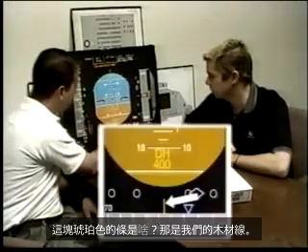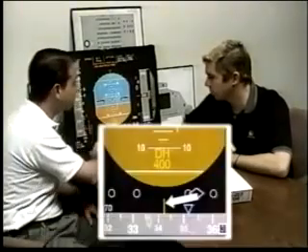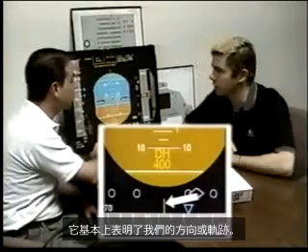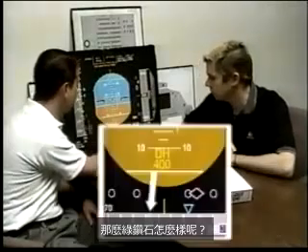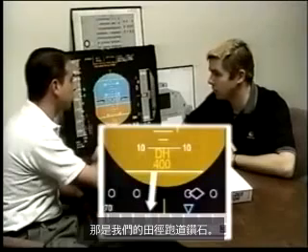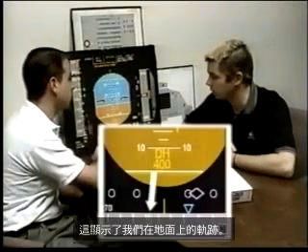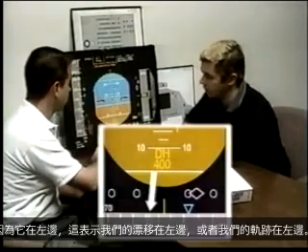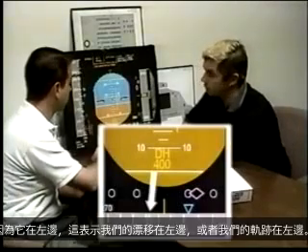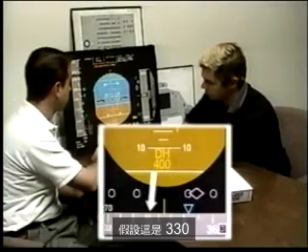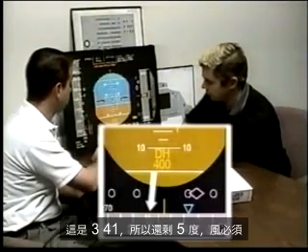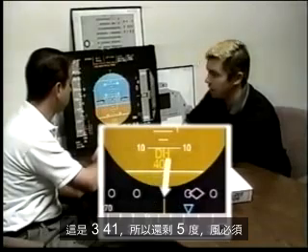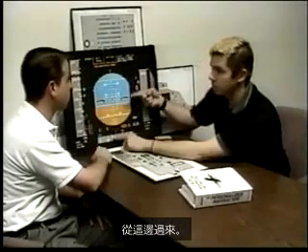What's this amber bar right here? That's our lubber line. It basically indicates what our heading or track is. And what about the green diamond? That's our track diamond. That indicates what our track is across the ground. Since it's to the left, that indicates our drift is to the left, or our track is left. Let's say this is 336, this is 341, so that would be 5 degrees left, and the wind must be coming from this side.